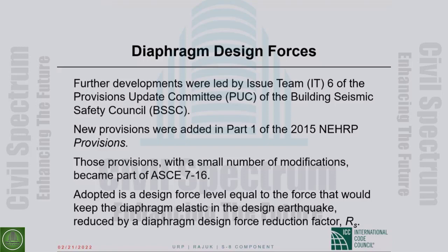So there is one question referring to a previous lecture. You have calculated live load reduction factor based on IBC 2009. R is equal to 0.08 times some area, where area is in square foot. The alternative approach for live load reduction factor is not available in BNBC 2020. Can we still use that IBC 2009 equation for reduction of live load?